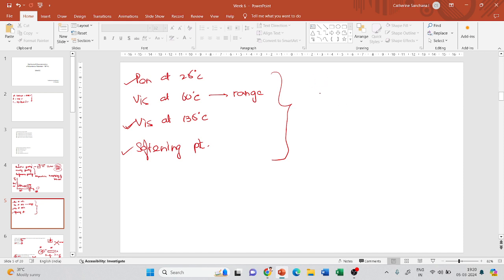Out of this, if my bitumen is VG10, then it has a viscosity of 1000 poise. If my bitumen is of VG40 grade, then it has a viscosity of 4000 poise. There we saw that if my penetration value is higher, then the bitumen is softer. But here, if the viscosity grade is lesser, it means that the viscosity is less and the bitumen is softer.